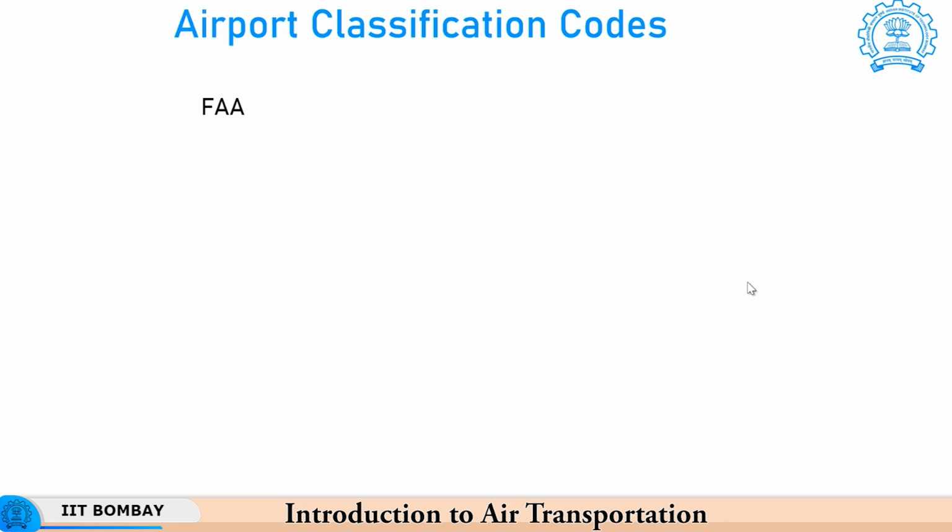First, we will look at the method followed by the FAA. FAA looks at the approach speed, V approach, of the aircraft, which is generally 30% higher than Vstall at the maximum landing weight and the aircraft in the landing configuration. This is generally the case. The approach speed of the aircraft is typically 1.3 times Vstall or higher, so that there is a 30% margin.